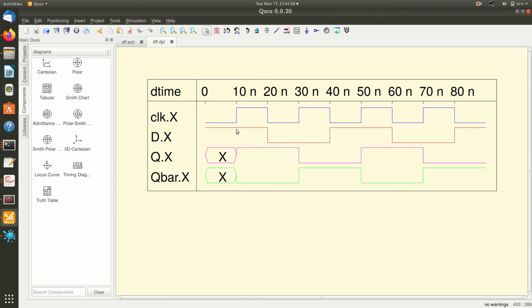So here at the clock the output becomes a high. This is a data input, it becomes a high, and this 0 comes here. So when this 0 comes, it does not change because it waits for the next clock. So from here you can see this delay. This has become 0 at this point, but that gets reflected here after half the clock cycle. So you can see that this output appears at the output with some delay.